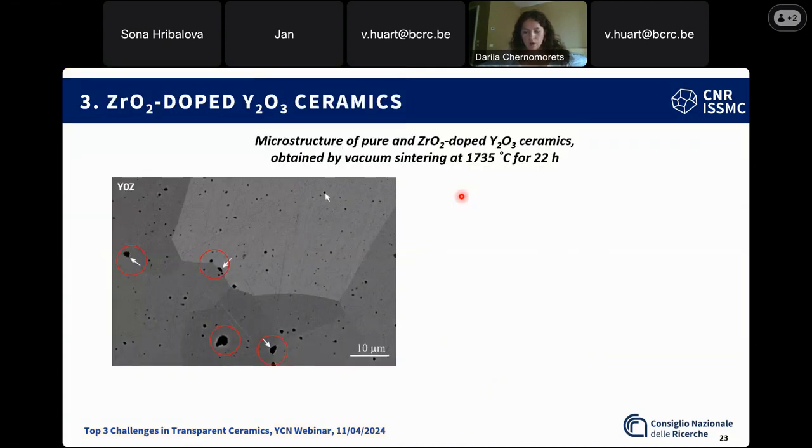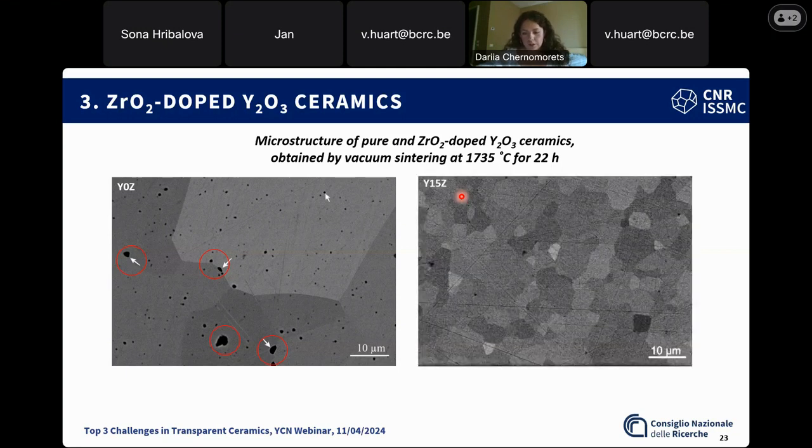If, for example, you reached full density and then afterwards the pore-free material had some further grain growth, that should not really have any negative effects on the transparency. It might have an effect on the mechanical properties, but then it's not an issue. And that's what you have in lithium fluoride spinels. I mean, spinels produced with lithium fluoride sintering aid. You can have large grains, but you get rid of pores, and that's the main point.